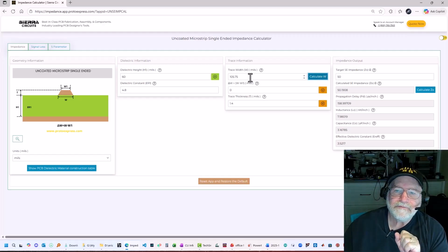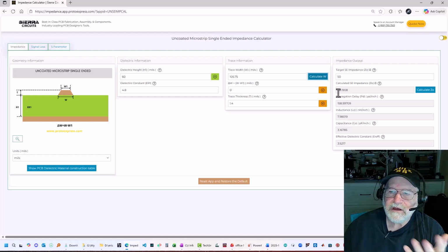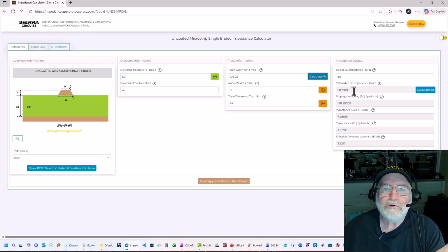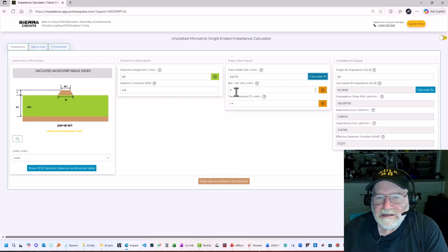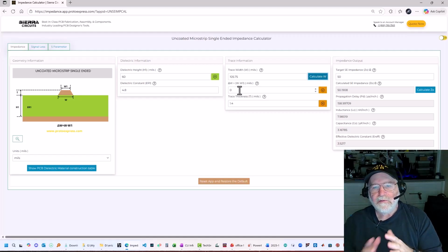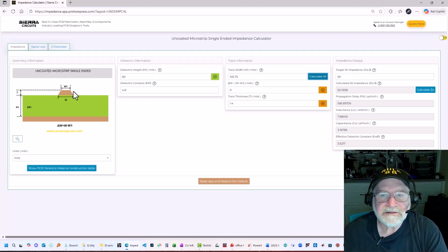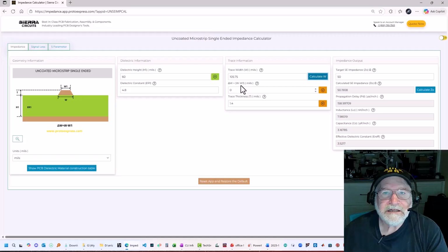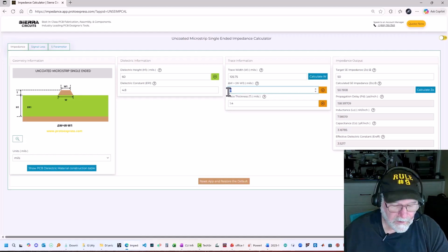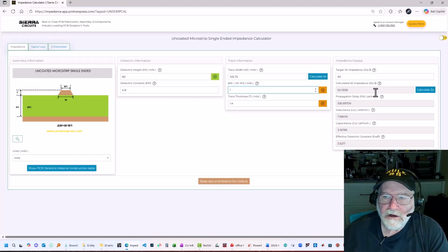While we're here, and we've just done this calculation and we've got an impedance of 50.2 ohms basically, we can ask the question, okay, if we make a small change, suppose that we had some etch back. Suppose the top of the trace was narrower by a half a mil on either side, so that's 1 mil. So our etch back was 1 mil. What would be the impact on the characteristic impedance?